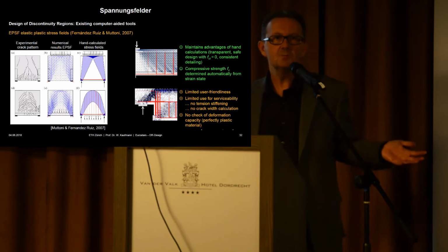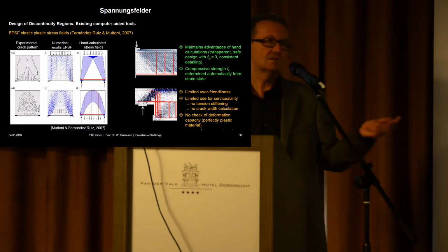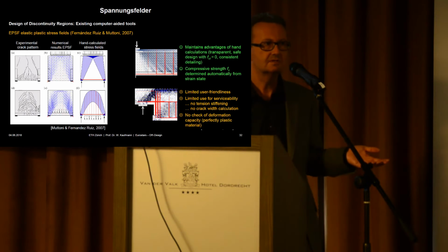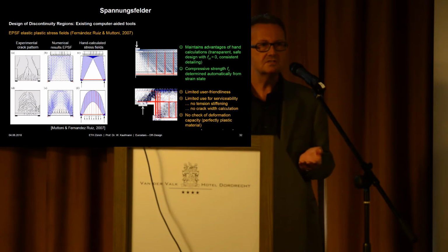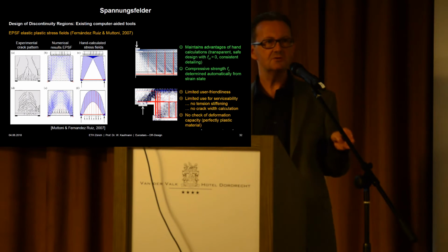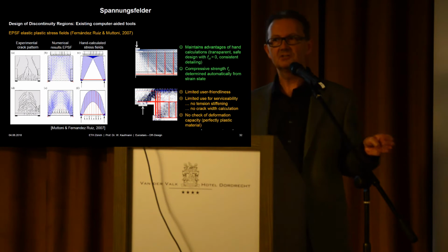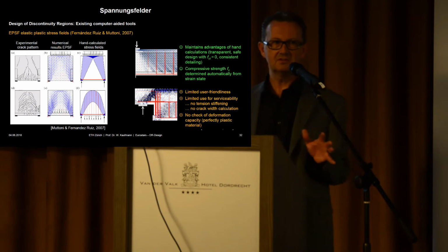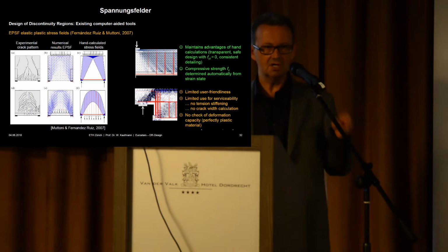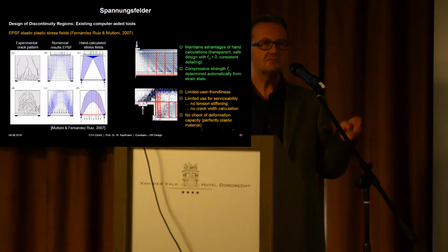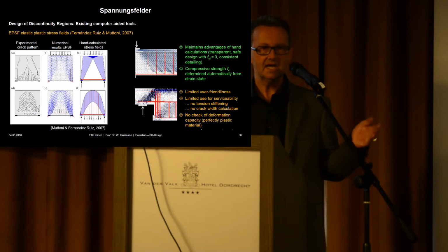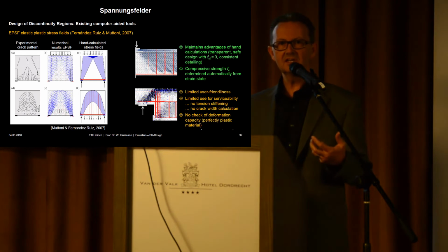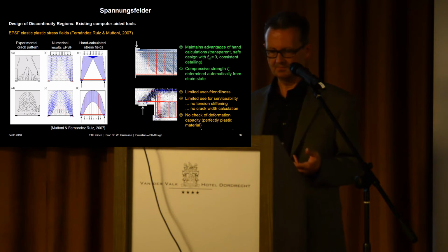Right? If you do a strut and tie model, do it by hand or with the StatiCa, actually, as said already, you can choose many solutions. And actually, I tell my students, the good engineer tells the structure how it should carry the load, and not the other way around. Not the structure tells you how complex your calculation should be. You tell the structure how it should carry the loads. You can simplify, don't make your life more complicated than required. And knowing what's behind these methods, you can ensure the right detailing to ensure that you have a safe design.